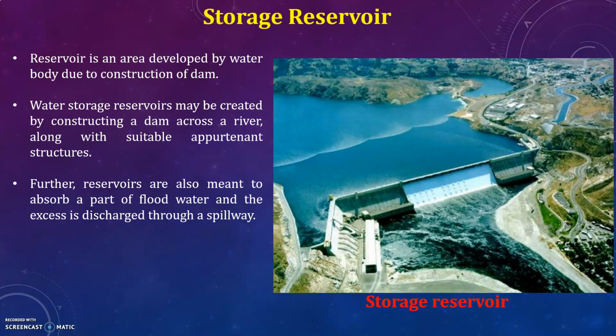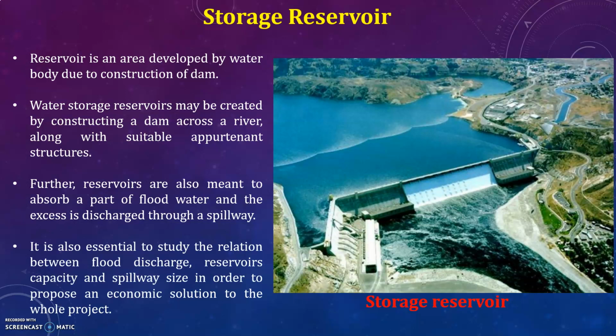Dams and reservoirs are the most important and expensive elements in multi-purpose river basin development. They require very careful planning, design and operation. A number of problems arise in design, construction and operation of dams and reservoirs. It is also essential to study the relationship between the flood discharge, reservoir's capacity, and spillway size in order to propose an economic solution to the whole project. This, you can see, is a storage reservoir.